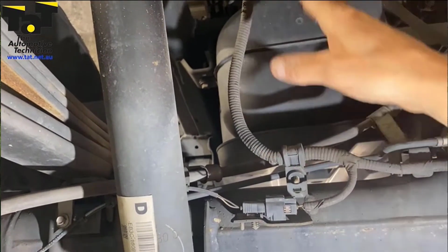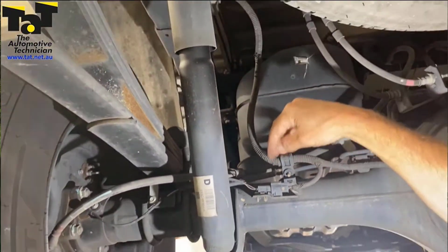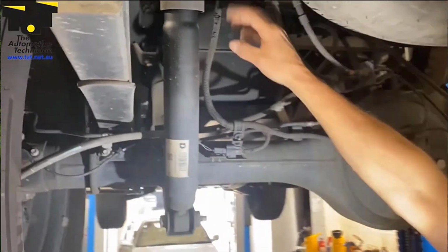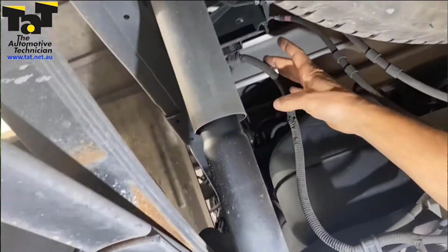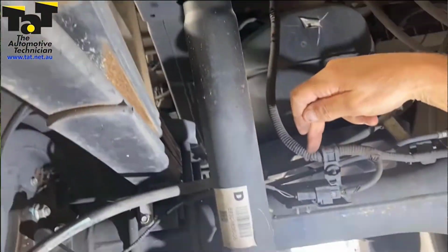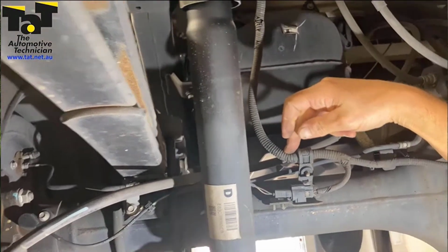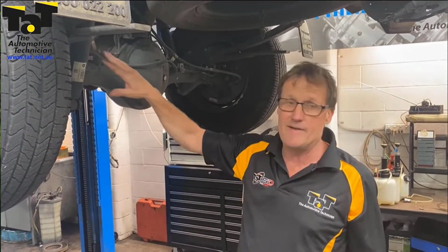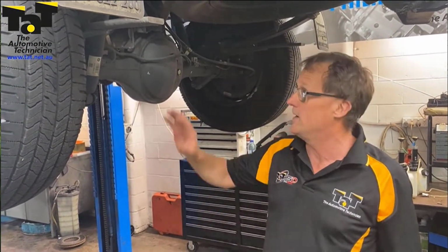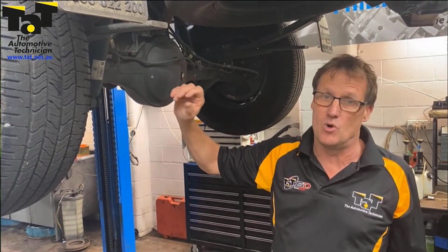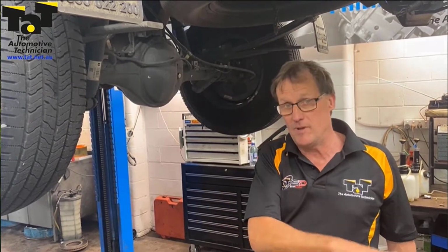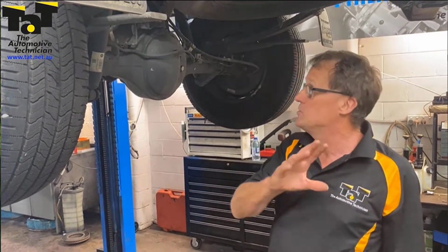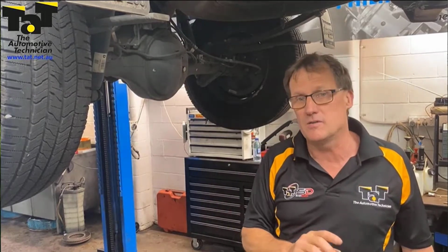So if you've got any issues with these sorts of vehicles, make sure you have a really good look at this wiring harness here and at the top, because that's where they traditionally break, up at this point, or even more importantly right here at this point here. So again, if you're working on one of these vehicles, have a look at it when it's on the hoist. You're in for a service, have a look to make sure that wiring's in good order. They are commonly breaking in that particular point. As I say, we've got a case study already, a repair solution on our system, which we'll highlight as well, but that's the common area to make sure we have a look at.